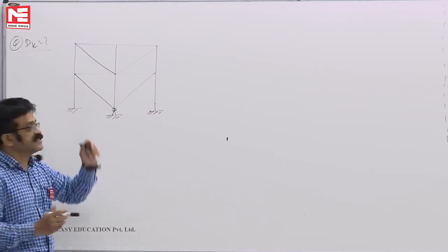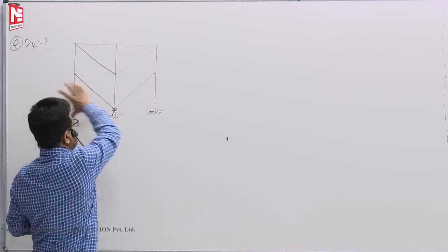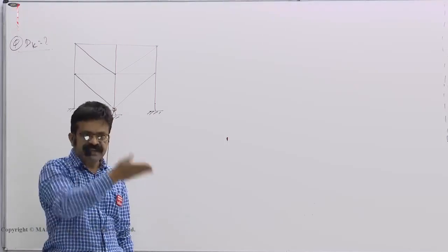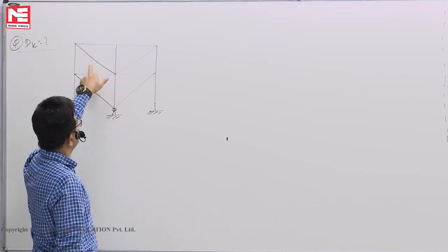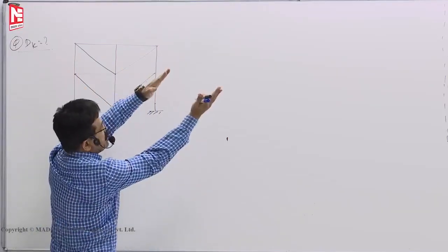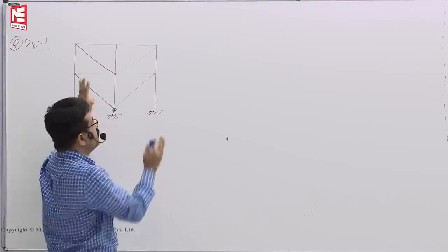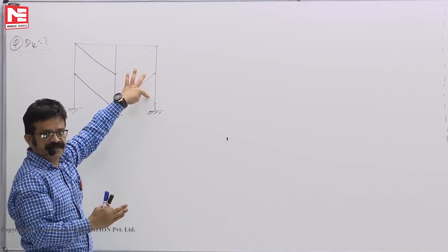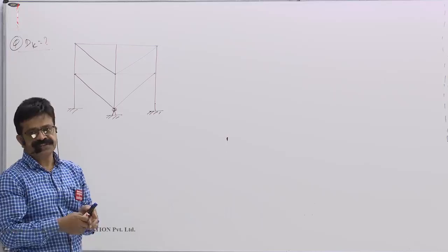First, we will take up the general case. Now, you see, these members are there, this is like bracing. In this floor level, for one floor level, one bracing rod is enough, the other will also, two directions sway, it will stop. So, 1, 2, 3, 4 bracing rods are there. Out of that, you have to count only 2. If at all it sways to the right side, okay, so this will be under tension, these two are useless. If it sways to the left side, then these are under tension, this will be useless. Okay, we assume that bracing rods are ineffective in resisting compression.